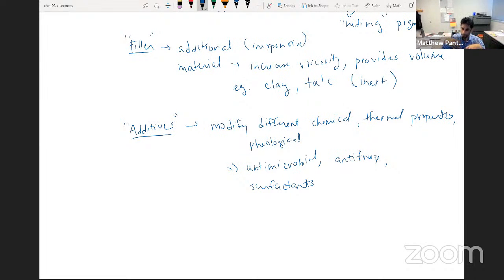From a molecular point of view, they found that to be the biggest way they can get cost savings from paint: formulating it differently such that these TiO2 particles would not aggregate and stay a certain distance away from each other. So surfactants and other types of polymer additives can contribute to that.